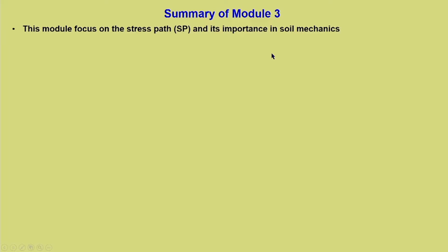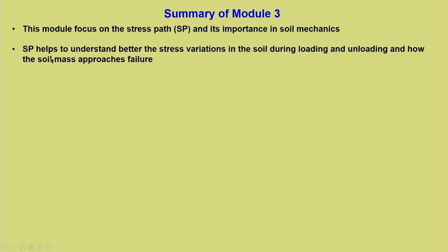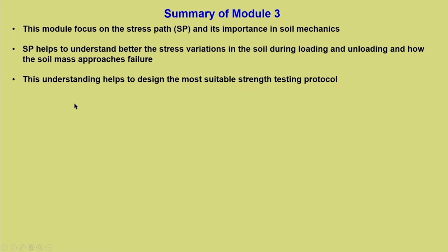So, this module focuses on the stress path and its importance in soil mechanics, which I hope you would have appreciated by this time, how important stress path is. Stress path helps to understand better the stress variations in the soil during loading and unloading and how the soil mass approaches failure. It gives a very clear representation, which we have tried to demonstrate in a few of our lectures. This understanding helps to design the most suitable strength testing protocol.